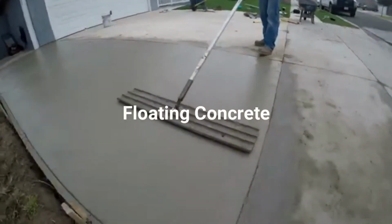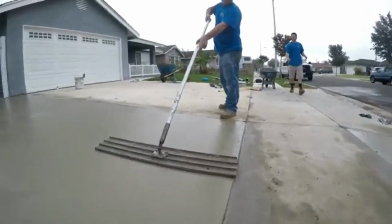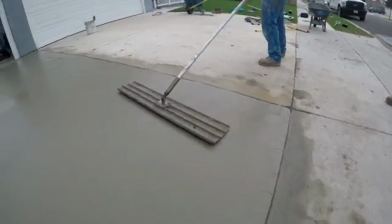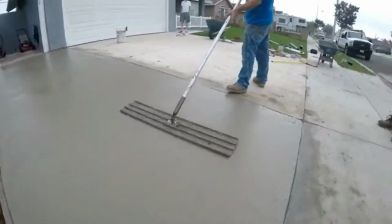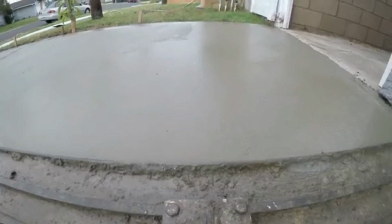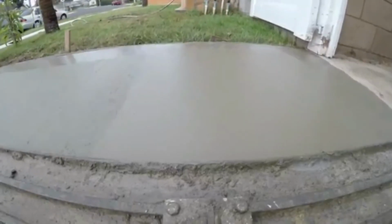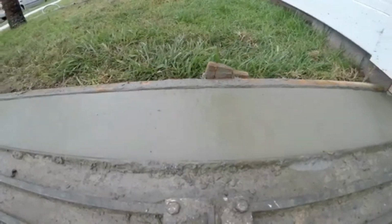Floating concrete. After the concrete has stiffened, floating is done by the cement finisher. A tool called a wood float moves back and forth over the surface until it is level and no coarse aggregates can be seen. Floating the surface is done to be sure that there is only a smooth mixture of cement, sand, and water on the surface. No coarse particle should show. After the concrete has been floated, a final finish can be put on. Sometimes, a float finish is used as the final finish.